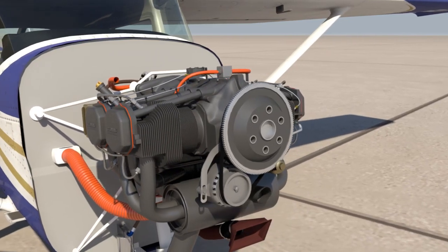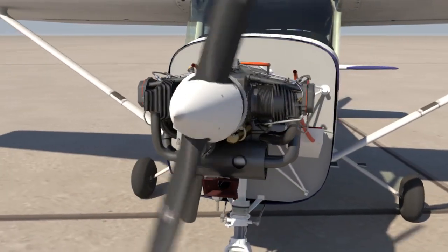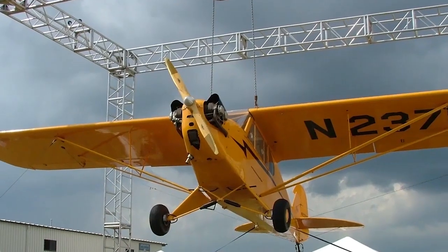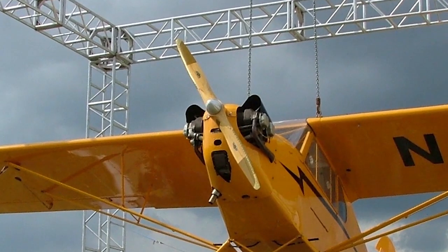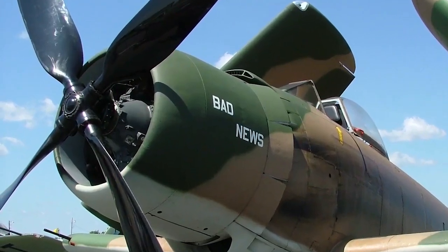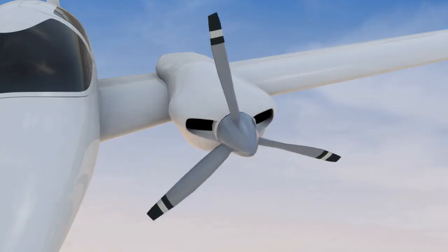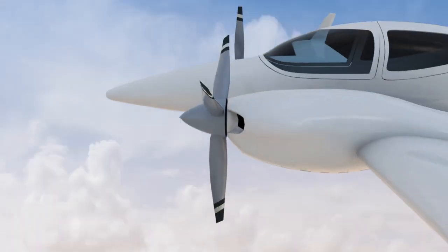With reciprocating engines also comes the requirement of a propeller. Just as there are different engine configurations, there are also different types of propellers. These propellers can range from the simplest 2-bladed propeller made of a solid piece of wood to a complicated, multi-bladed propeller with additional built-in features. These features can include the ability to shed off ice, or even to change the blade angle during flight. The rotating of the blades is similar in purpose to a car's transmission.